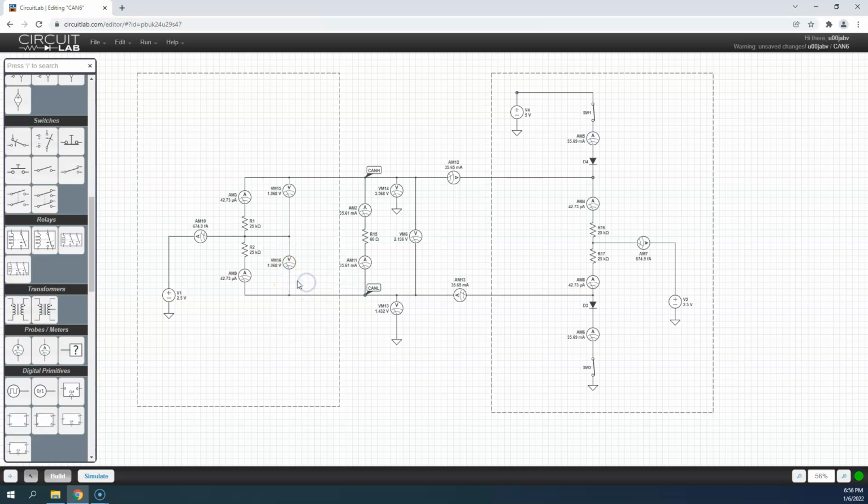And there we go, these are positive together, 1.068 volts. There's this magic law that says if I add up all the voltage drops, they have to equal the resulting voltage I would measure across all of these. So this is 2.136, 1.068, 1.068.